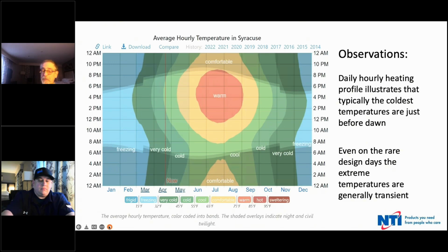The algorithm says if we're running and not seeing a temperature rise, the logic is that we're not putting out enough energy to increase the temperature in the building. So the boiler, if you've enabled boost, and you really should, will automatically look at that and start raising its outlet temperature to match what it feels it needs to do to warm the building.